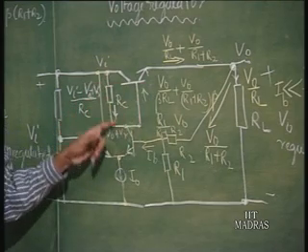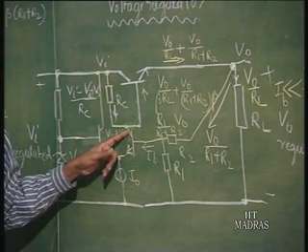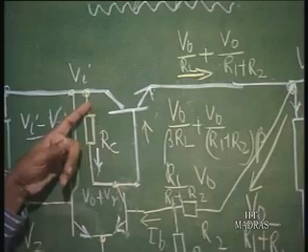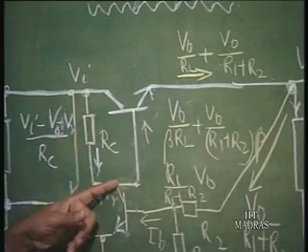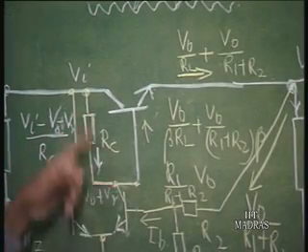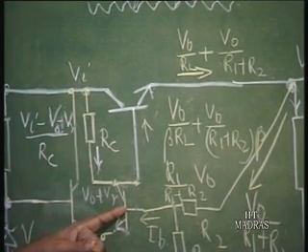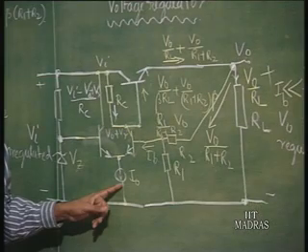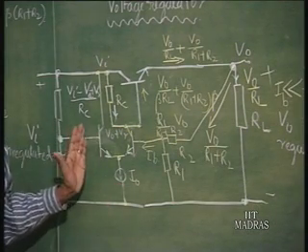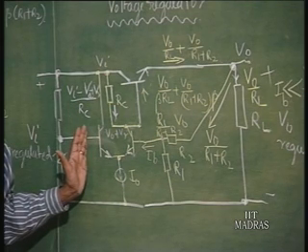So, this current has to be greater than 1 milliampere. Let us say it is 2 milliamperes for a given input voltage. So, this 1 milliampere will go into this. Therefore, I naught has to be greater than 1 milliampere, so that some current is left out for this transistor to remain in the active region.